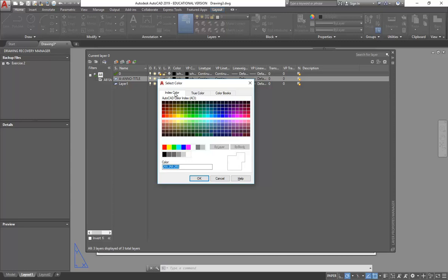So they're the ones that pick up the line weights, and the colour will be set to black. Right, so that's probably what's wrong. Yeah, that's right. We'll go more into this later, but for now, just stick with index colours because we want everything to print black. Those index colours are there just as a guide for you. And for things like text, we often just stick with white.